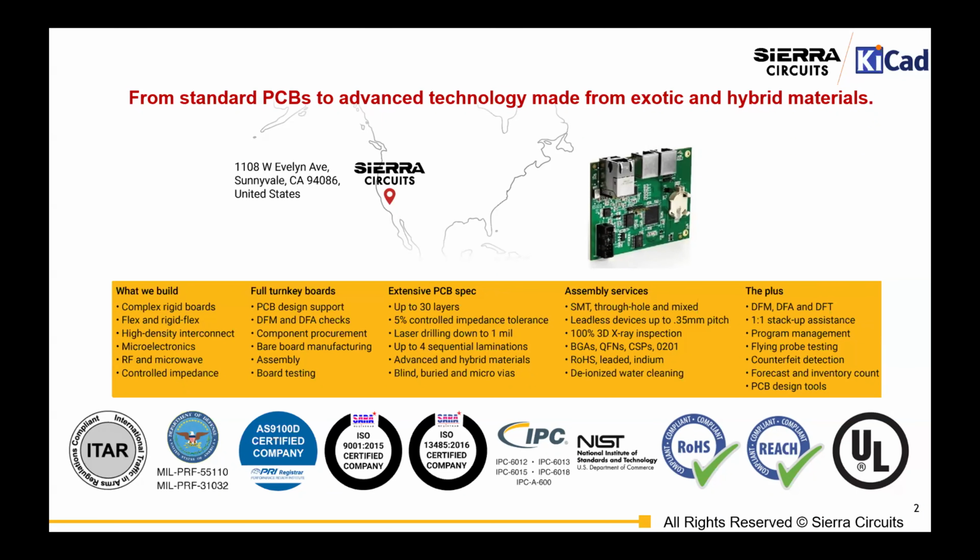Okay, got it. And this is just for my education: all these rules that we're talking about, they're real time? DRC check is a step you take after you have designed a portion or all of your board. While you are routing, for instance, DRC clearances are accounted for. So that is a real-time check while you're routing, and you will see the errors pop up when you violate one of those rules during real-time routing.